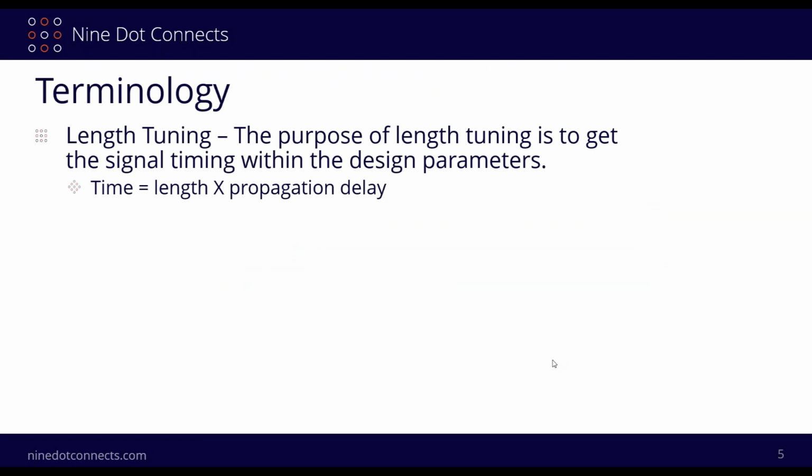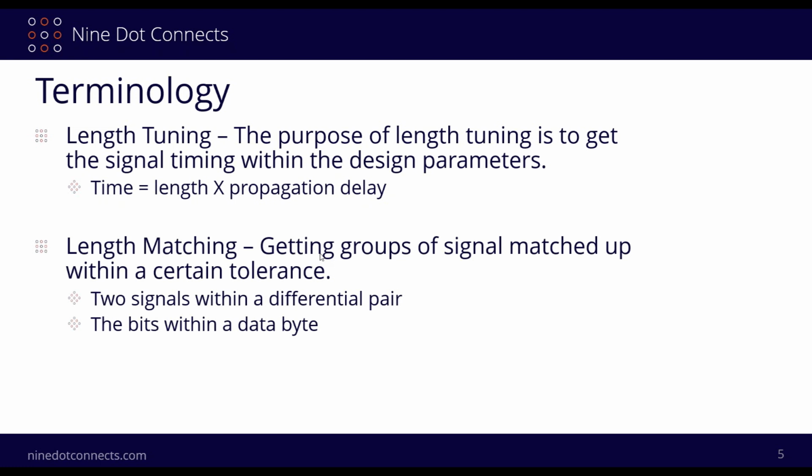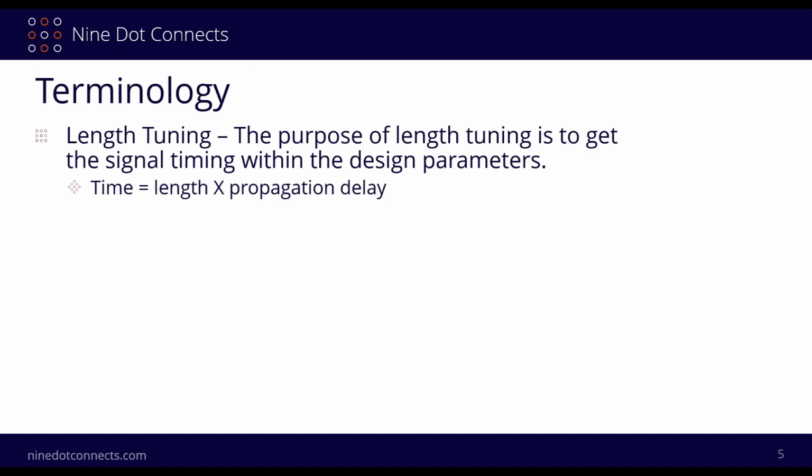I want to talk about some terminology for a moment. There's a lot of discussion about length tuning and length matching, and I want to talk about length tuning first. Length tuning, from our definition, is really taking the length of a single signal and adjusting it accordingly so that it is within the design parameters.